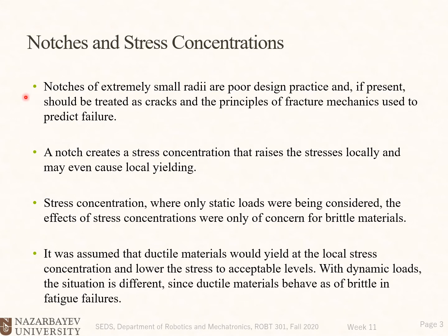Notches of extremely small radii are poor design practice, and if present should be treated as cracks, and the principles of fracture mechanics used to predict failure. So we don't know what fracture mechanics is. We don't study it in this course and in this book. Okay, so just put that aside. It's beyond our knowledge, and it's something that should be avoided. For normal circumstances, we should avoid fracture mechanics.